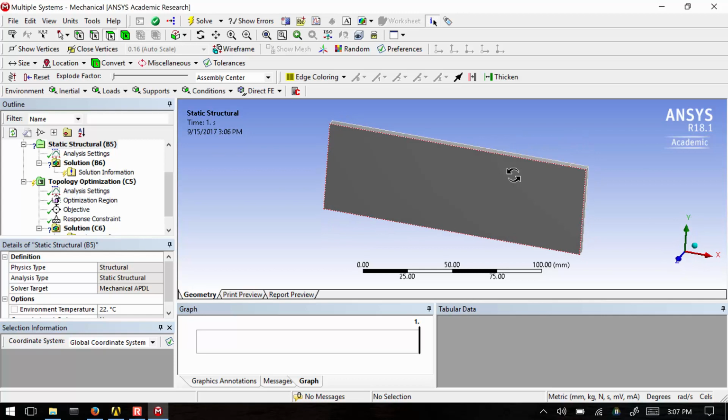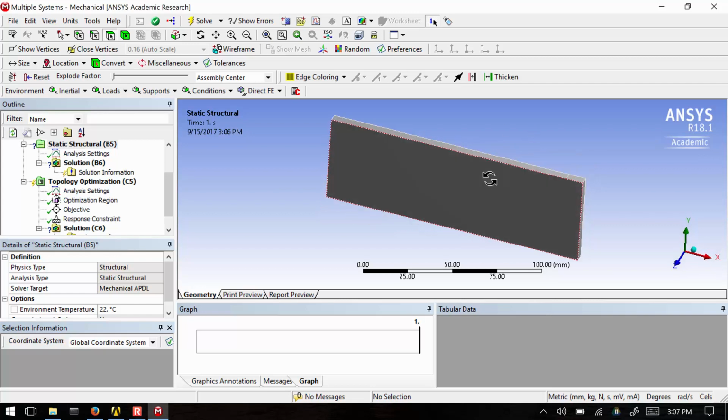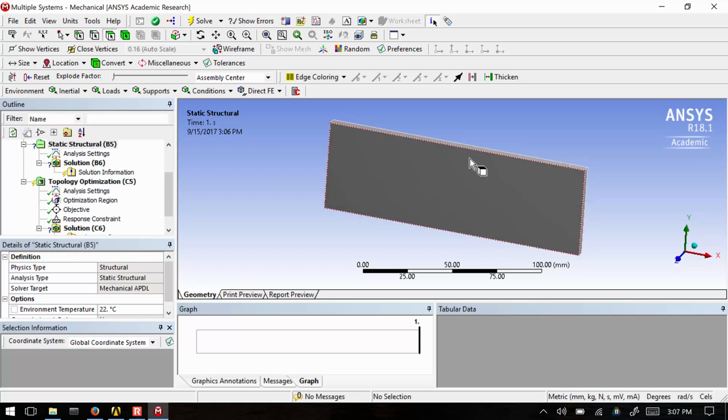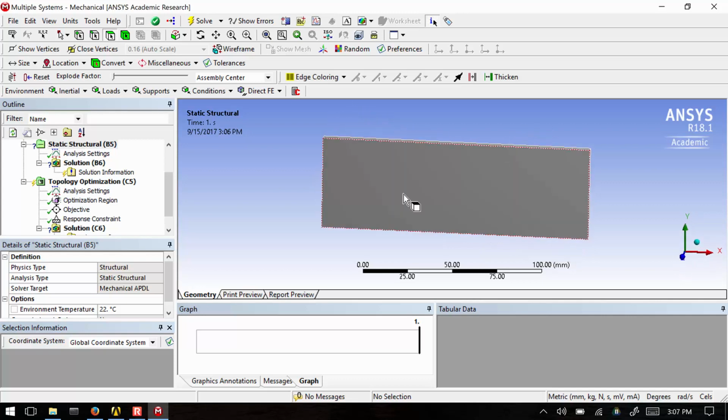And what I want to do is minimize the mass of this. I want to have stress be below a certain threshold to minimize the mass. So I'll go through that exercise. You usually define fairly simple geometries to start with, and it'll remove material from this to get to your design, as we'll see. So it's important to make that envelope big enough. And it's usually fairly simple like this.